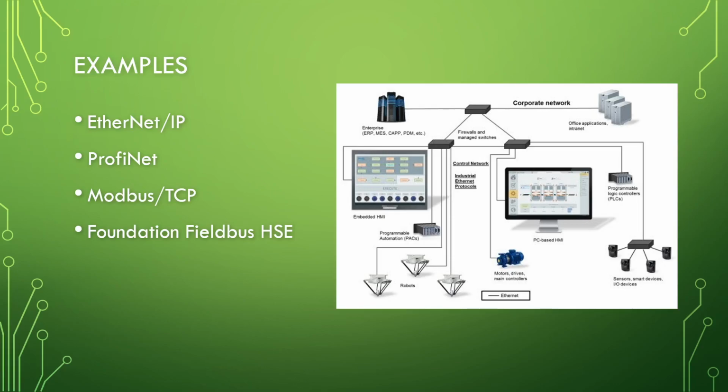We might see Ethernet IP. IP, as I said, is industrial protocol. This performs at levels 5, 6, and 7 of the OSI. The CIP, the Common Industrial Protocol, that's those top 3 layers. Ethernet packets used with this protocol of CIP, TCP/IP, or UDP layers provide the required data to your controller. So kind of pick what we want to be transmitting information on. This does promote consistent implementation of automation functions across a diverse ecosystem of products.